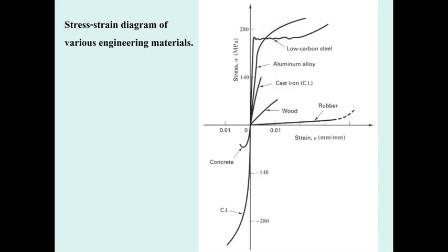Okay, next, let us use this stress strain diagram and try to understand the definitions of strength, stiffness, elasticity, plasticity, and even energy capacity. On this stress strain diagram, there are two parts. One is the result from the tension test, and the other is the result from the compression test. Some of the materials are good in compression, such as concrete. Most concretes have good compression